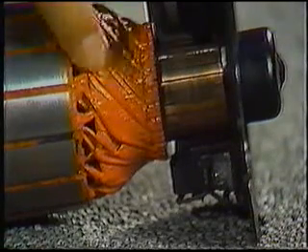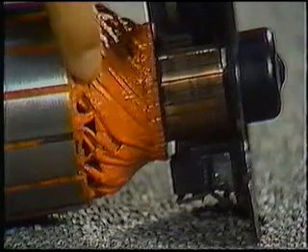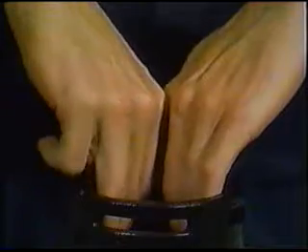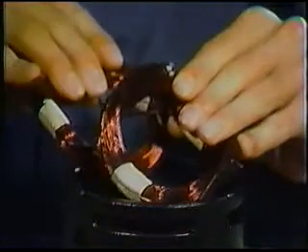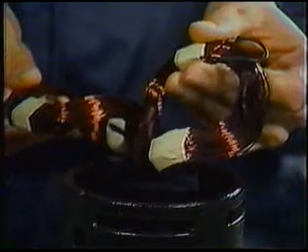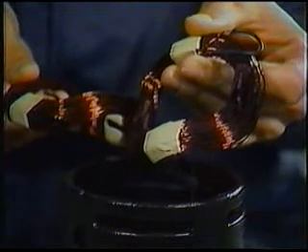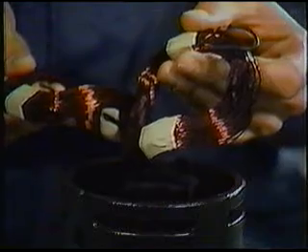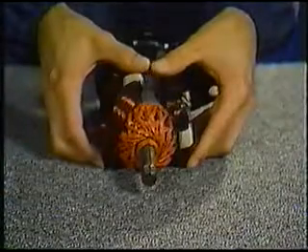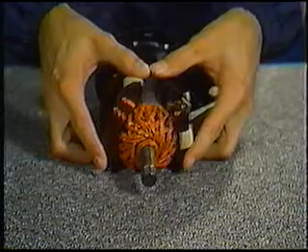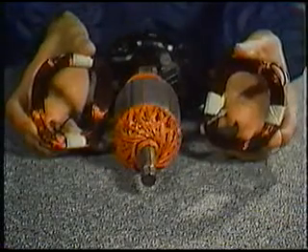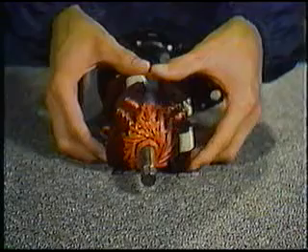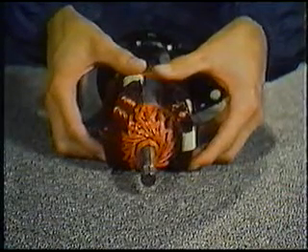Each of these segments is attached to a group of wires that essentially comprise one loop. Inside of the generator housing, we find no evidence of a horseshoe magnet. Instead, loops of wire are wound around forms to produce an electromagnet. Remember, the amount of magnetic flux an electromagnet will produce is dependent upon the amount of electric current we flow through it. By using this type of design, we can vary the strength of the magnetic field by varying the amount of current flowing through these windings. Not surprisingly, they are referred to as field windings.